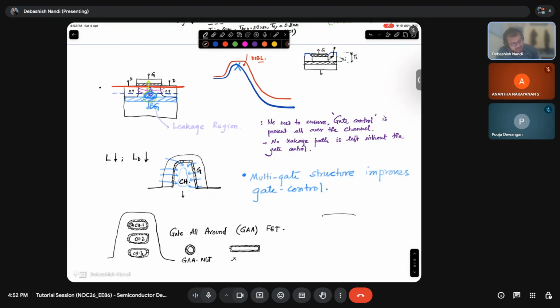So we call it nanosheet, GAA nanosheet FETs, right? And from that, fork sheet and CFET we'll discuss in the next session. Okay. So just for your understanding, today's technologies of 3 nanometer technology and some technology nodes beyond that will use this kind of nanosheet structure where this is your gate and then there will be substrate here.